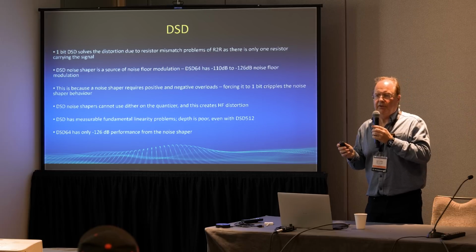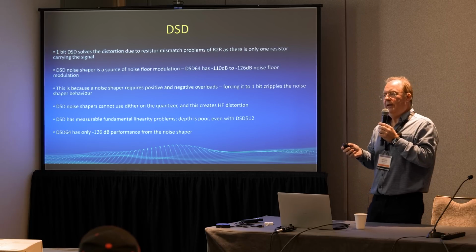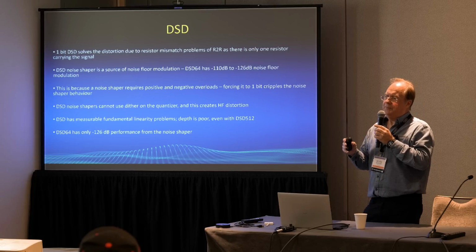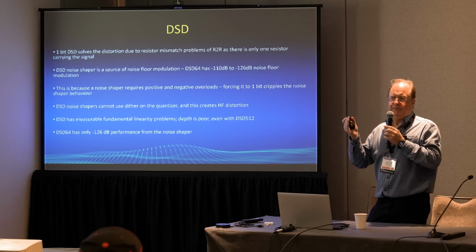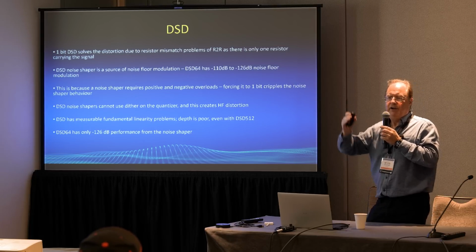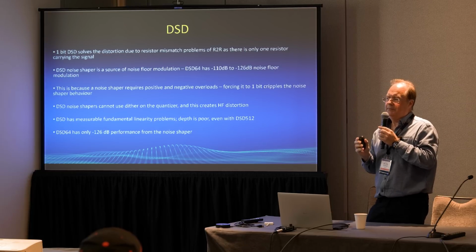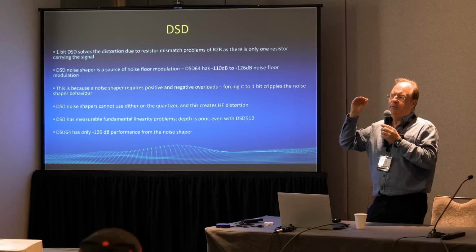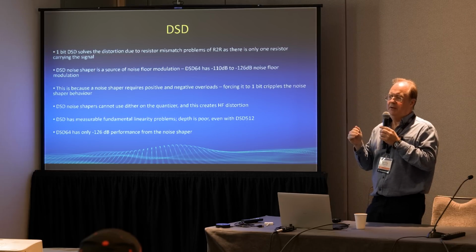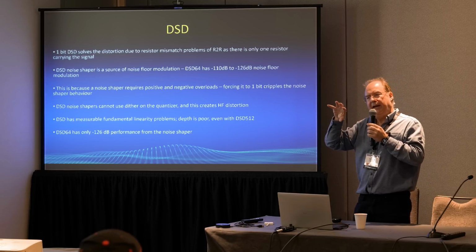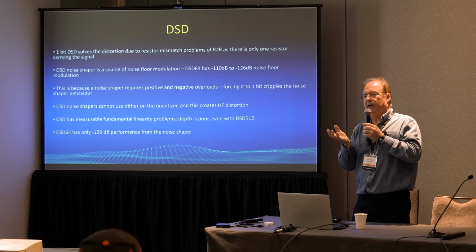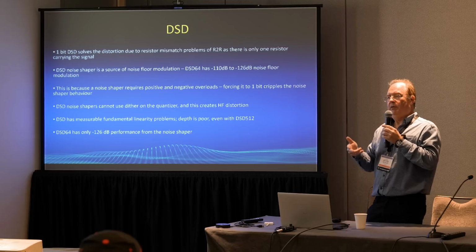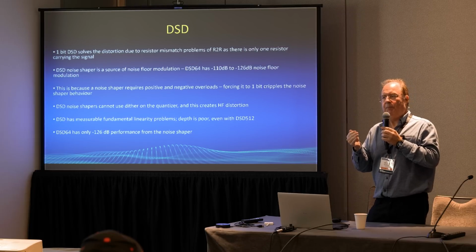But DSD's got a problem, and the problem is that it's 1 bit. When you're designing noise shapers, a noise shaper likes to go either a little bit too high or a little bit too low, so it needs overload. If you just limit it to +1 and -1, there are times when the noise shaper is saying, I want to be +2, and it cannot be +2. What will then happen is there'll be internal overloads, or it'll go unstable in the worst case, but the noise shaper will misbehave and it won't behave appropriately.